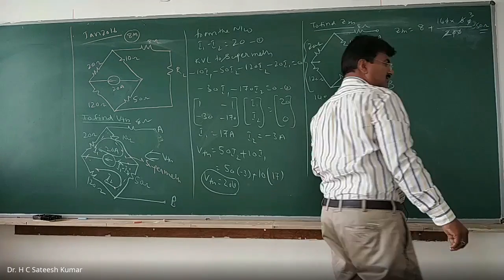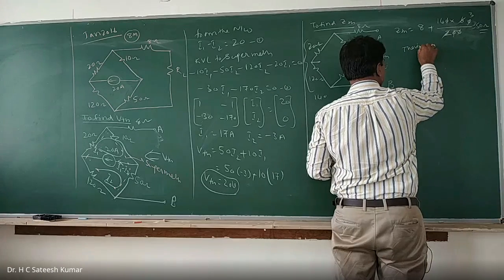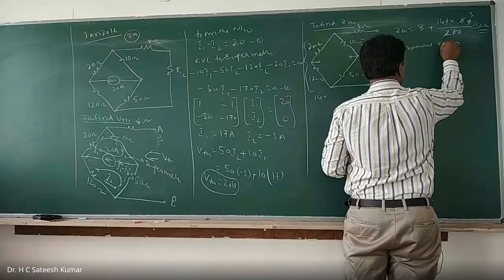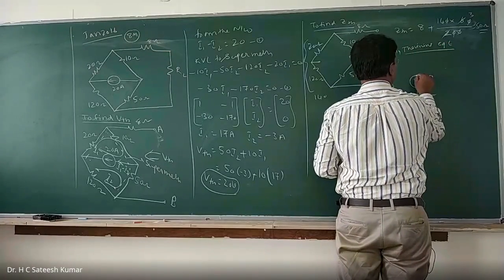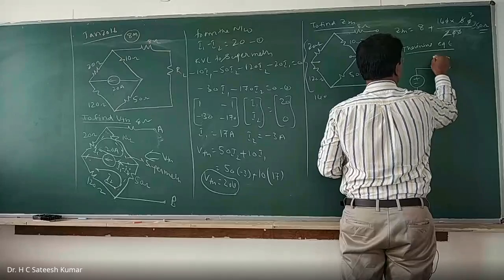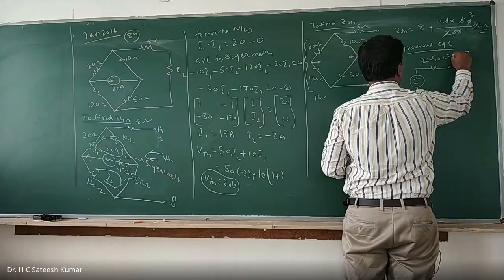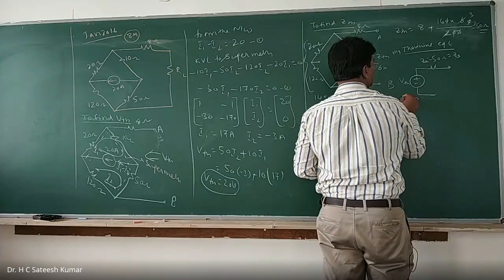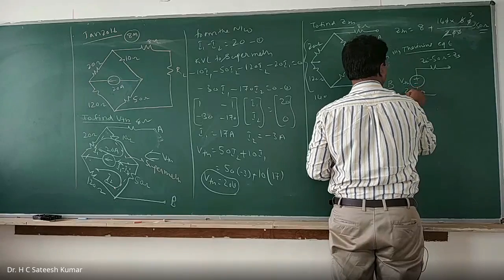Okay, right. Now, what should we do? Thevenin's equivalent. Third step. I'll write the Thevenin's equivalent. Voltage source in series with the resistance, we can write it. This is 50 ohms, ZTH. That becomes Z source. And what is this one? VTH is equal to your VS. VTH is how much? 20 volts.